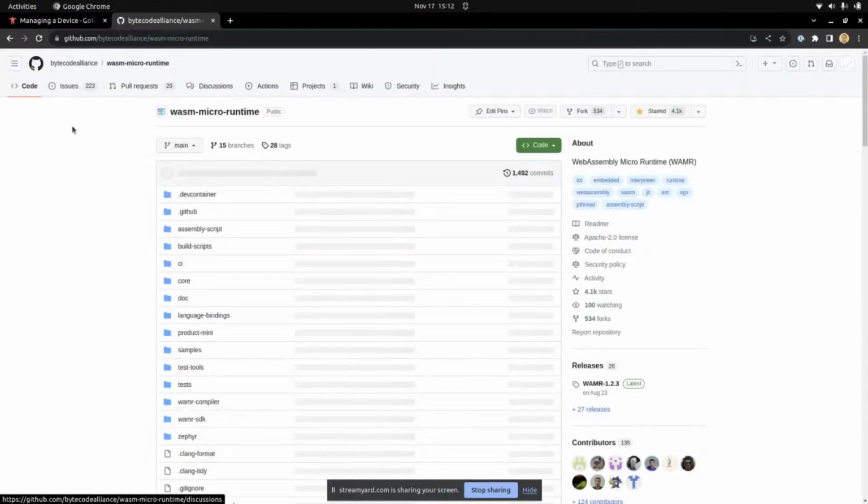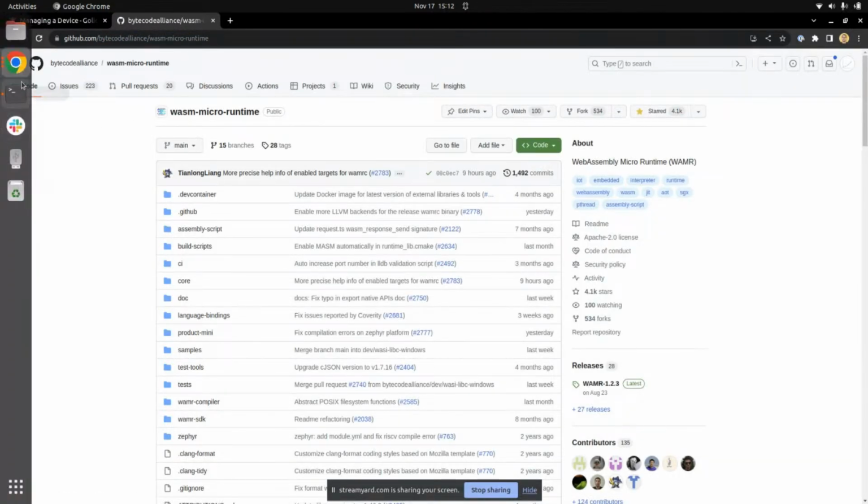What hardware is this, Dan? This is here. Yeah, I'll go ahead and pull it up here. And I don't have the StreamYard up, so you'll have to let me know if I'm actually adequately getting this in the frame. So I'm using the Nordic 52840 dev kit here. And then in order to get Wi-Fi support, I'm using the ESP32. I think this is a C3 module here. So I'm using the AT Wi-Fi bridge here to be able to talk over Wi-Fi with the 52840 on this dev board.